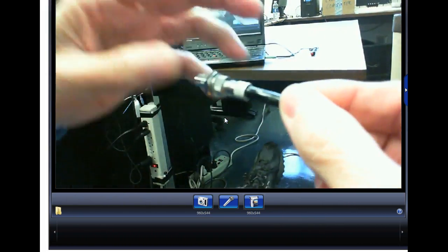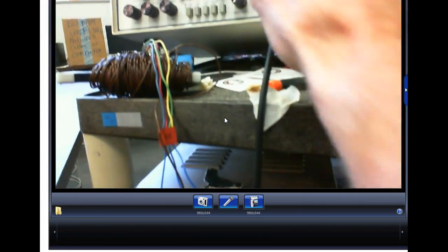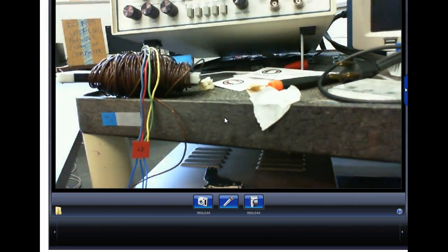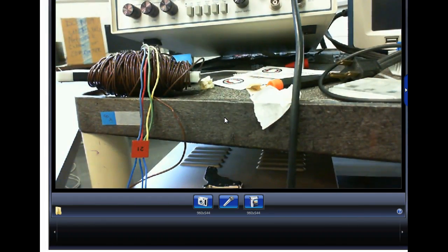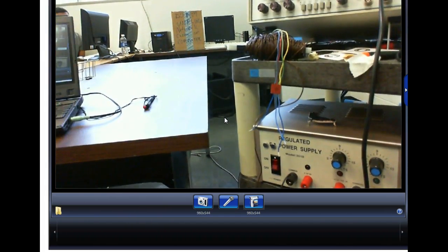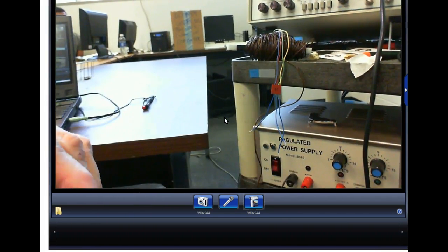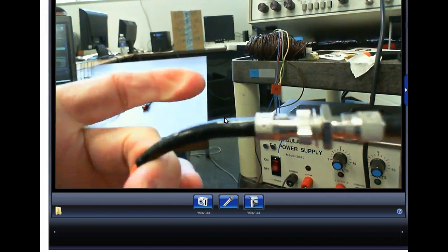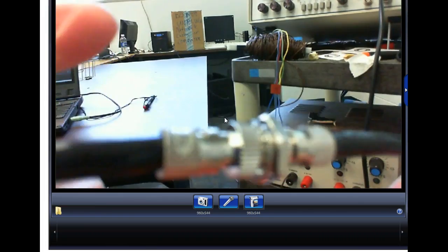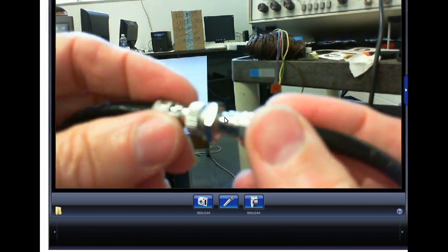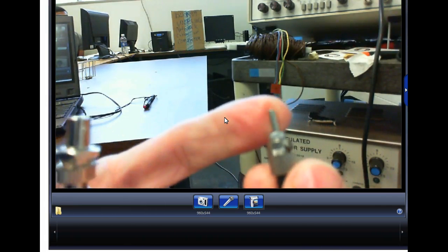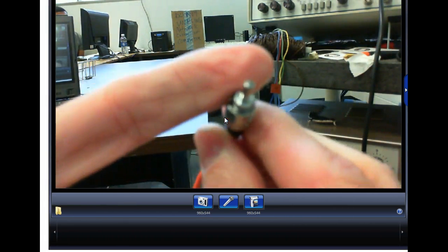These are the same connectors we use for our oscilloscope, and these guys right here are also bayonet connectors. So it's got a spring in it that does what? It pulls it in, and then it latches down. So what I could do with this is I could come here and do this, right? So we can connect two cables together that have already been terminated. Now this is not the way we would splice it. So you can see the different parts of the connector that are used to not only align but actually protect the fiber itself.